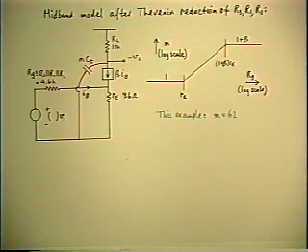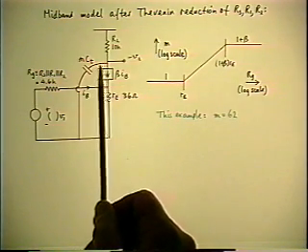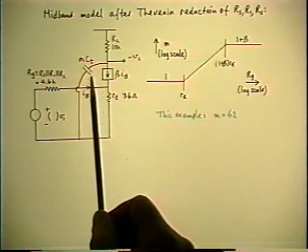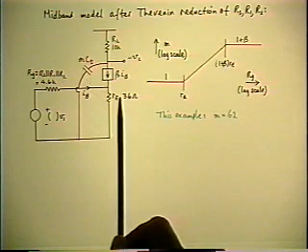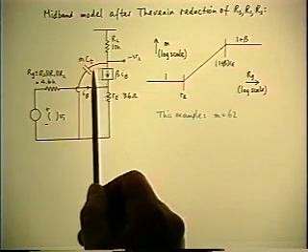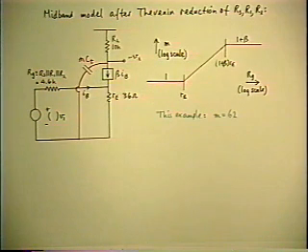Now, you've heard about the Miller effect before, and you usually think of it in terms of this interpretation, where the effective value of the capacitance is multiplied. You may also remember the Miller effect in the sense that the value of the multiplier is usually expressed as 1 plus the voltage gain of the stage. If that's A, then the effective value of the capacitance is 1 plus A times CT. Does that sound familiar? Is that the way you use the Miller effect?